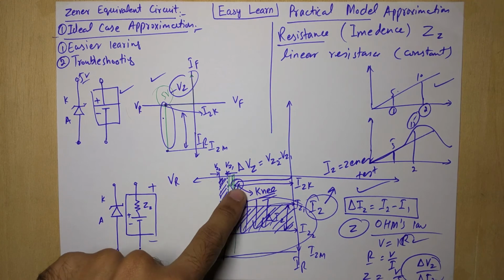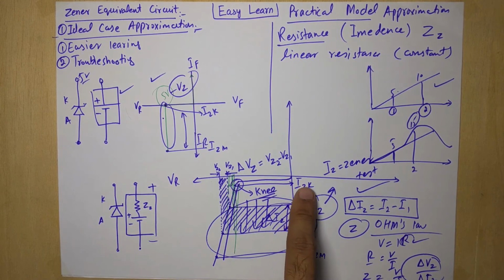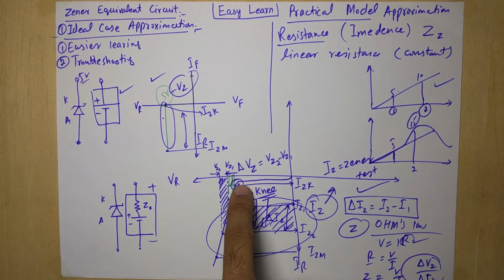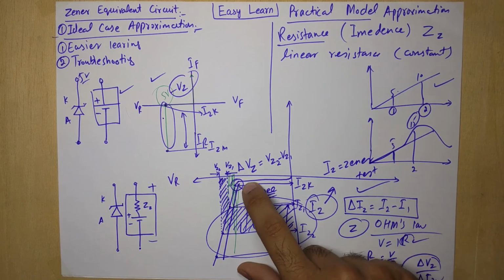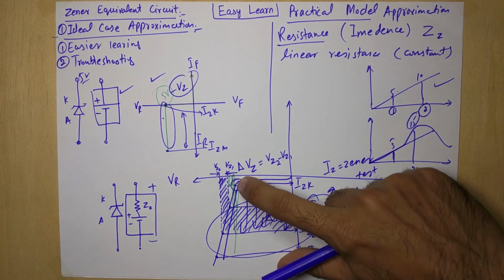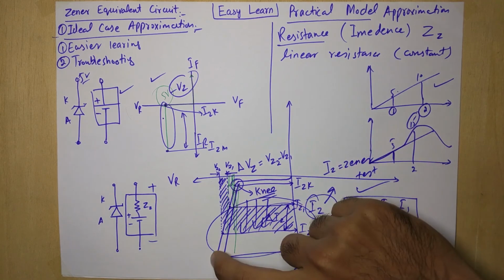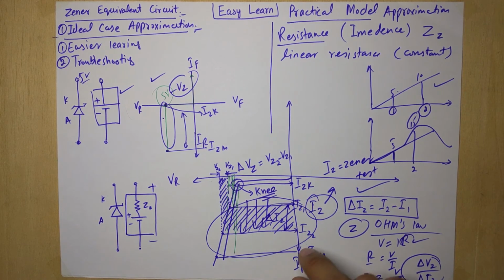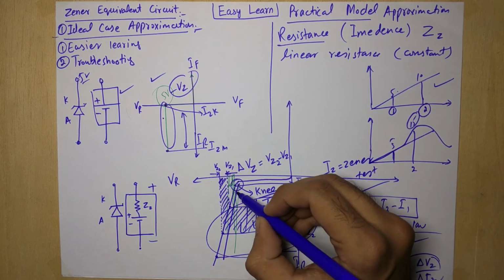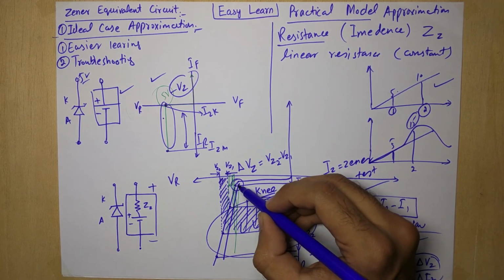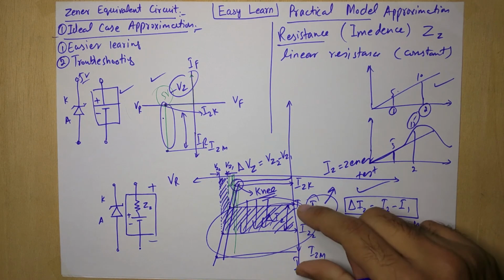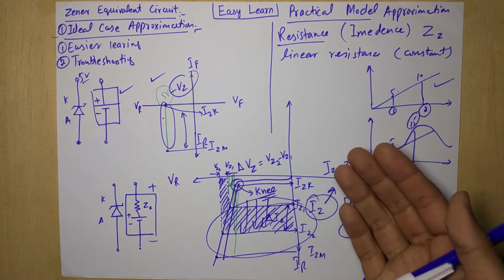In the case of current, the current is basically not increasing near the knee, just leakage. Then suddenly the current increases and the resistance reduces, with the push of current increasing. So if we operate closer to IZK and take samples, our sample value may go close to the knee and we may calculate the wrong value. So it's better to operate your Zener up from the lower value.